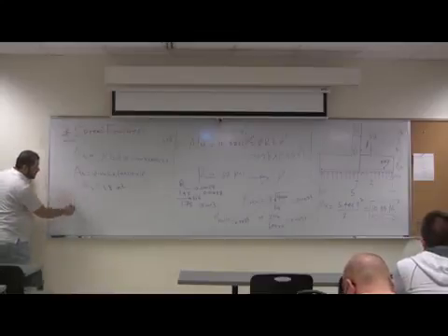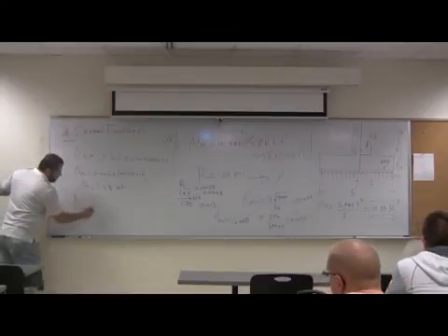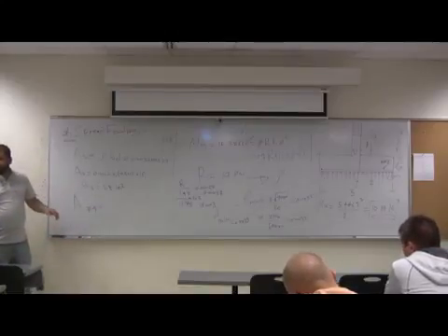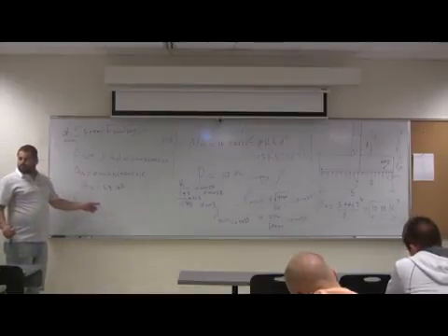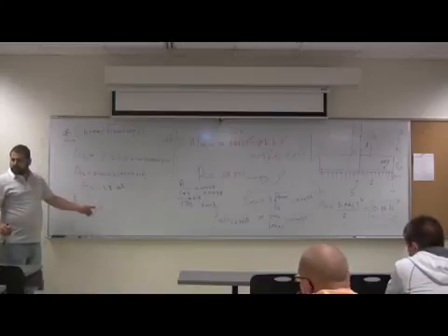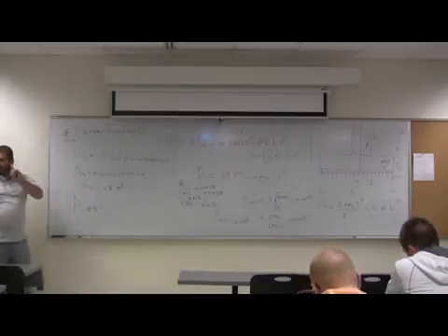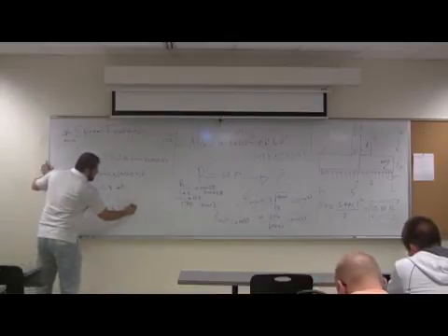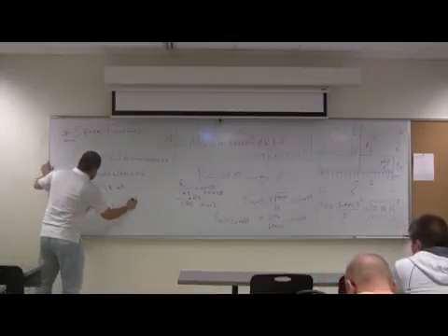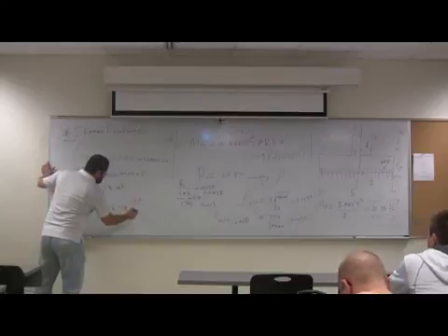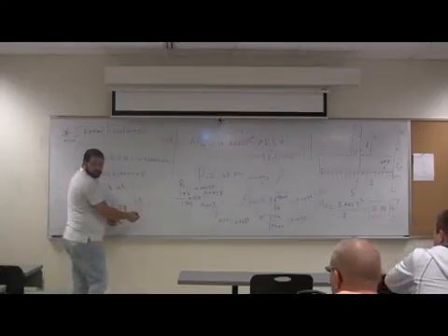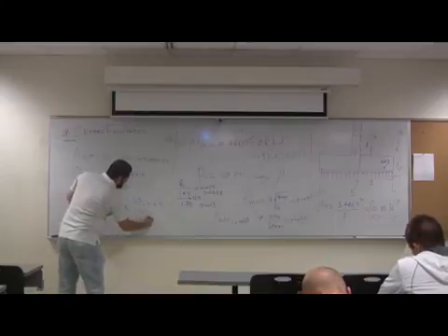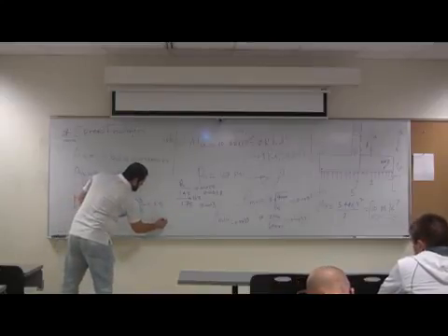What's the area of one bar of number 4? 0.2. So 1.3 divided by 0.2 equals 6.5. Use 7 number 4.